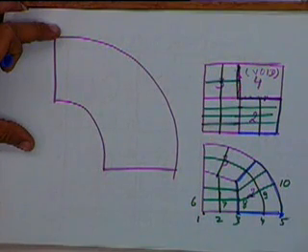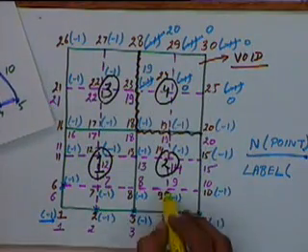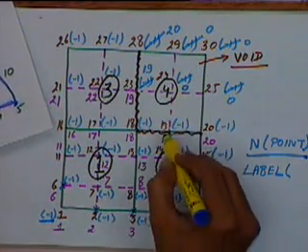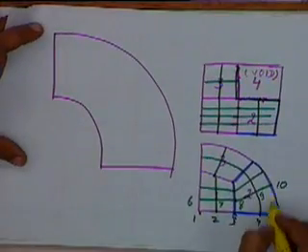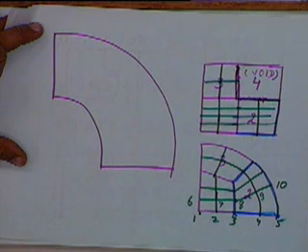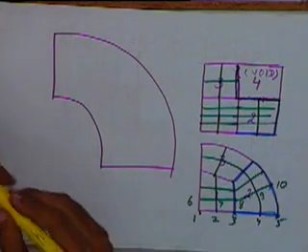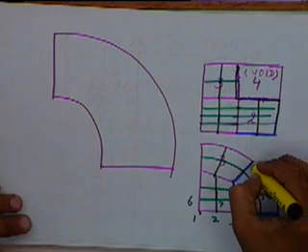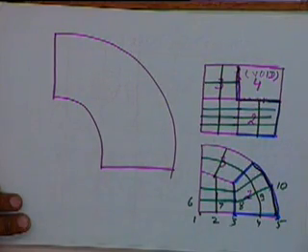Not just the edge lengths, we can take these nodes, the corner points, and then for getting the intermediate points, all these points, we can do a simple quadratic interpolation between the nodes. We can get these points by doing a quadratic interpolation. So effectively the actual element that we will get will have a straight edge over here, similarly a straight edge here and a straight edge here, if we are taking elements with straight edges.